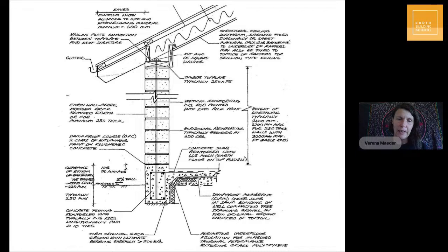The foundation has a couple of purposes. So the foundation can be in contact with moisture. It is strong, so it can take the weight of the walls, and the solid earth walls have substantial weight, even if you go to low density adobe. So you need to have good foundations. There's always that saying, an earth building needs good boots and a good head. So the boots are the foundation. The foundation transfers the weight of the building into the ground, and it has to stand on solid ground.